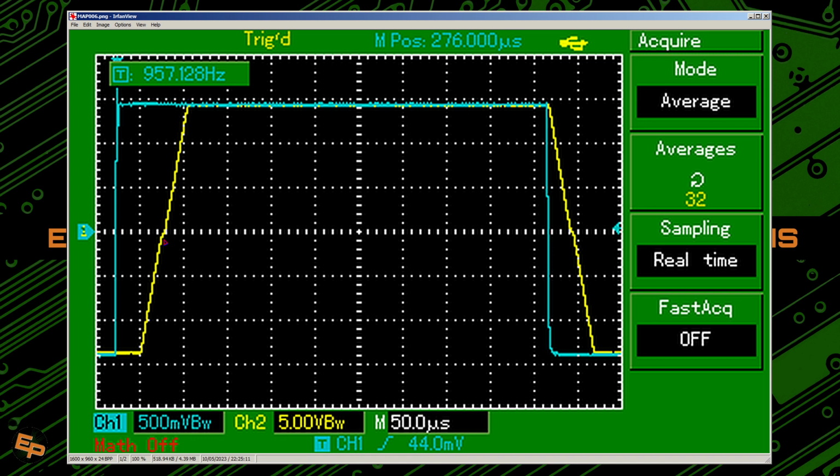And then of course it stays at the absolute maximum value that it can potentially have, which is I think about 14 volts in this case. And then when the input voltage drops down to minimum, the op-amp is able to start its descent at the same time with the output voltage. So we don't have this phenomenon on the falling edge, but we do have it on the rising edge.